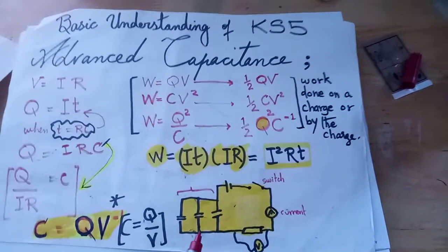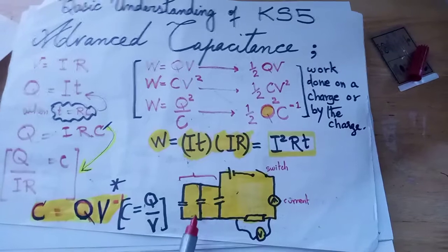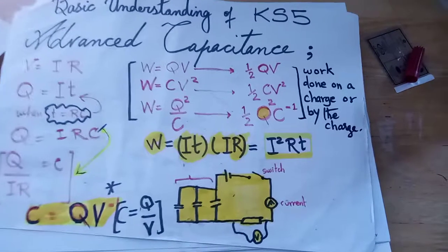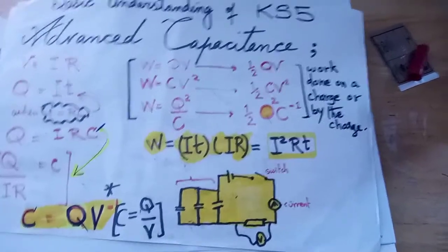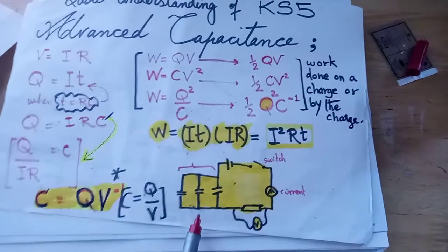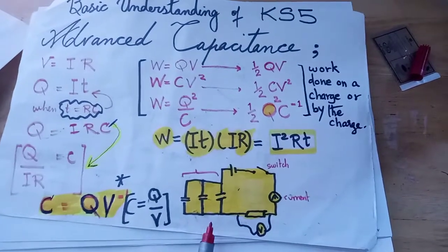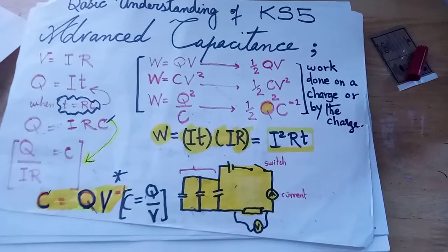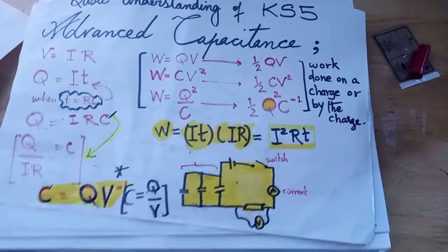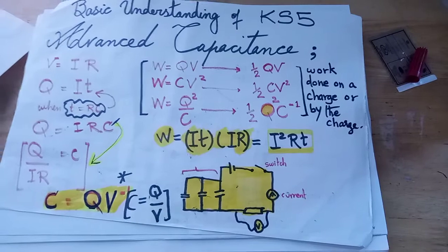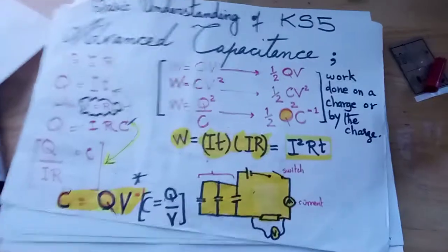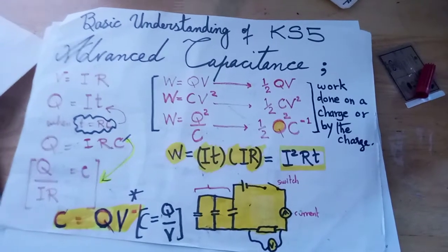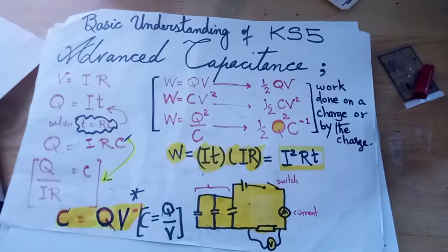The reason I've drawn this circuit is because, similarly to resistors, capacitors are calculated as well. The capacitance is calculated in a similar manner to resistors, but capacitors in parallel are calculated like resistors in series, and capacitors in series are calculated as though they were resistors in parallel.